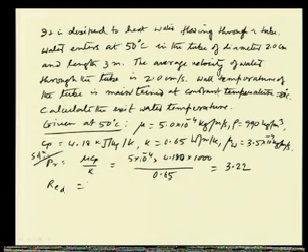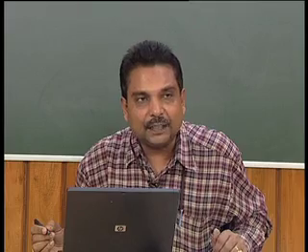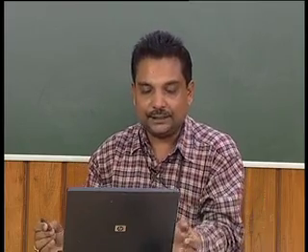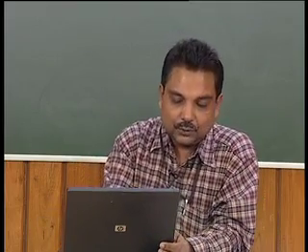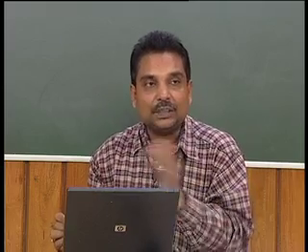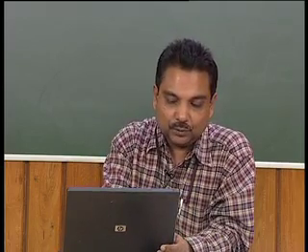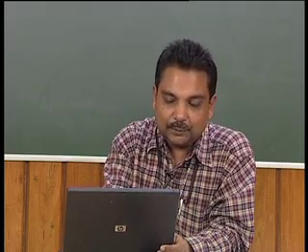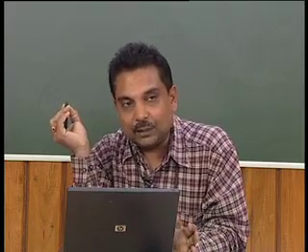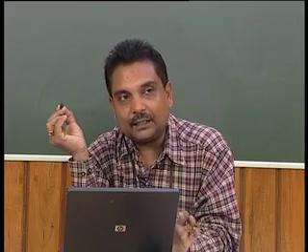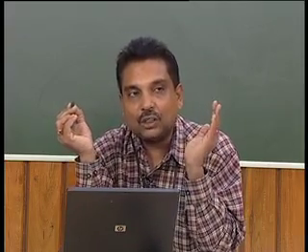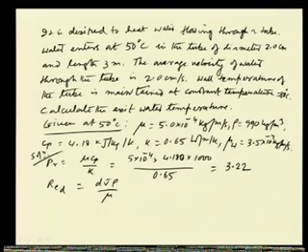and try to understand whether it is lying in the laminar region or in the turbulent region. That is what is very important to know, so accordingly we have to use a particular correlation. So, we will write now d v bar rho by mu, and we are calculating this Prandtl number and Reynolds number based on inlet temperature properties. All the calculations we are doing at inlet conditions, because we are given the values at inlet conditions.